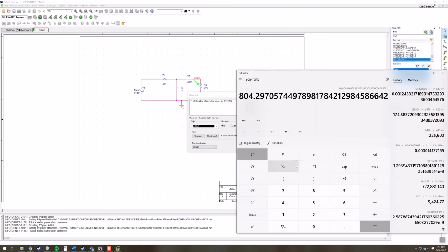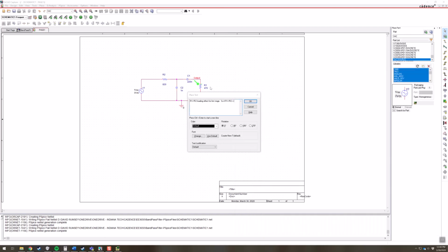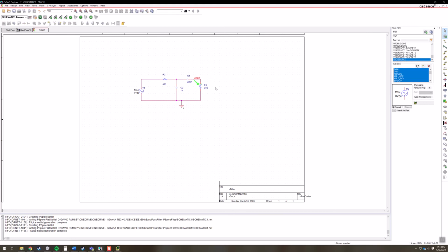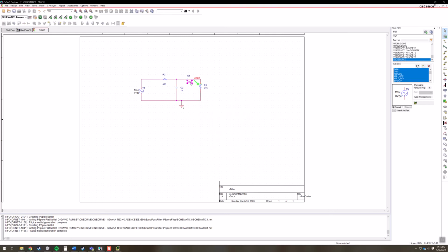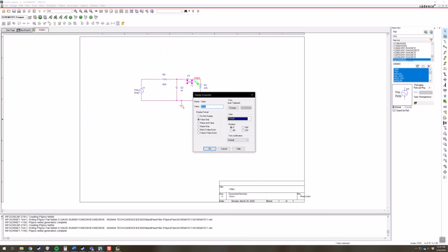We still essentially wind up with 820 ohms. Yes, it's reduced down to 805 or 804, but it's still essentially 820 ohms, and so the loading effect is significantly reduced. That's because in the original one, we made this 47 kilohms. So you absolutely have to have that there in order for us to not get that loading effect.